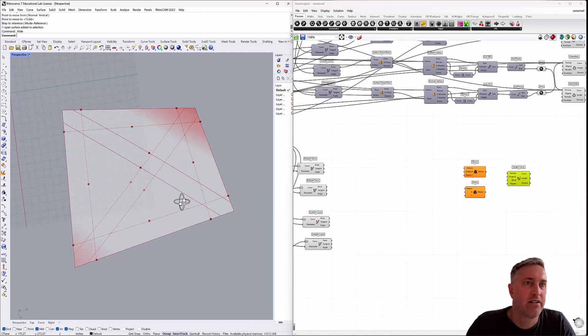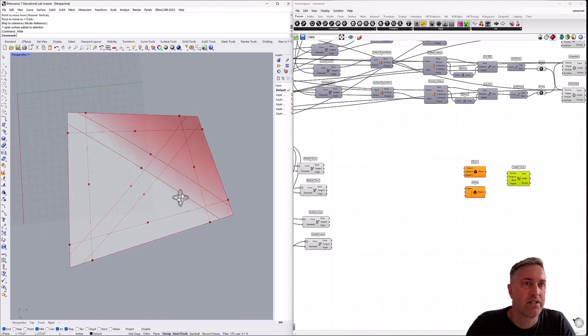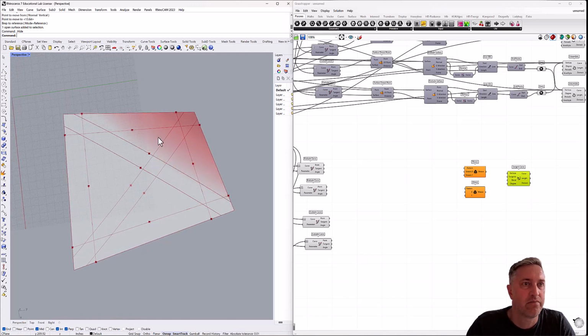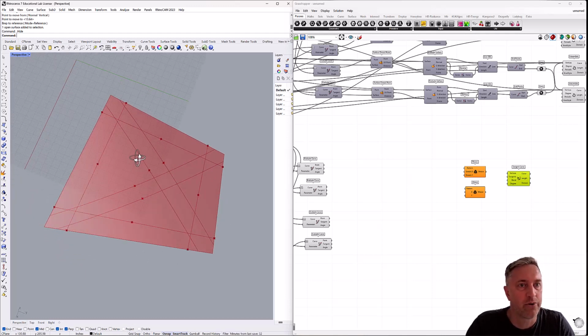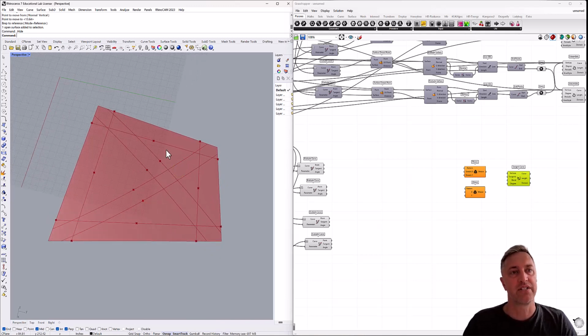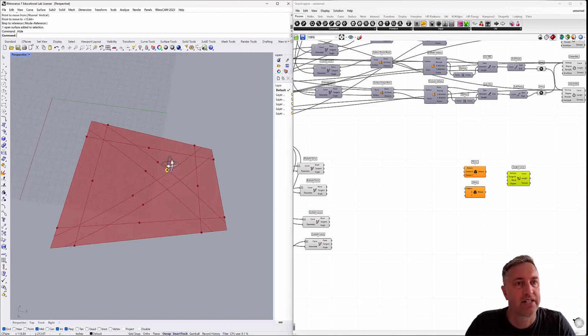What's going to happen is, it doesn't matter where we start. I'm going to go from this point, tangent along here, up to this point, and then tangent to here. All right, we're going to be, again, making this kind of continuous curve. And the reason why we're going to use the tangent curves is that when they get to the end, they're tangent and they'll meet up perfectly with the next line or the next curve.